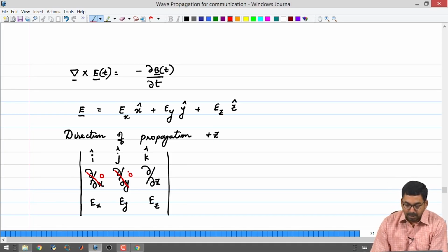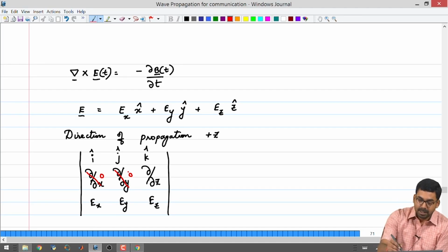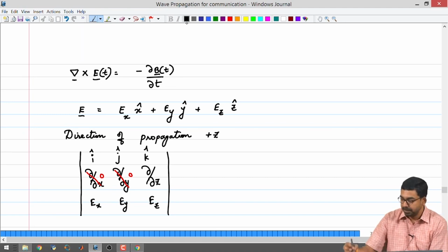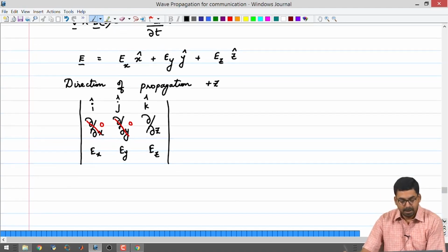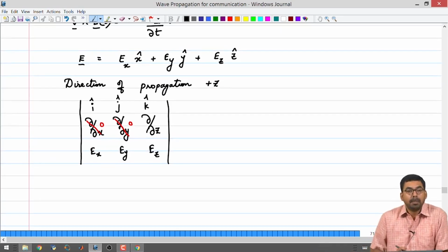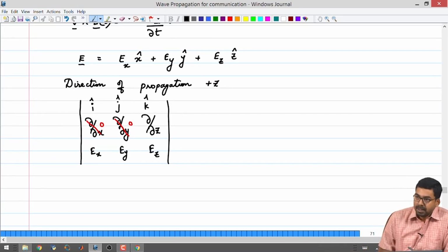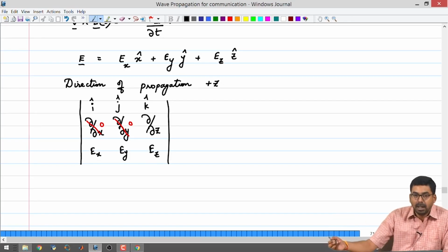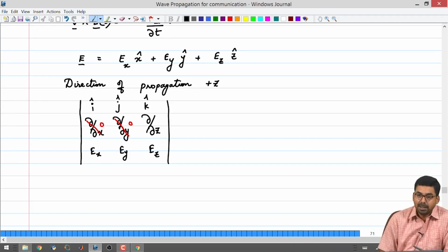The next step is to pick between Ex, Ey, Ez or a combination of everything. Let us say, for the sake of picking something, that we pick the direction of propagation to be z. Now, we want to estimate which of the electric field components can exist and which of them can produce a magnetic field on the right hand side. Not all the options are possible; you cannot have Ex, Ey and Ez, and I will show the reason why.